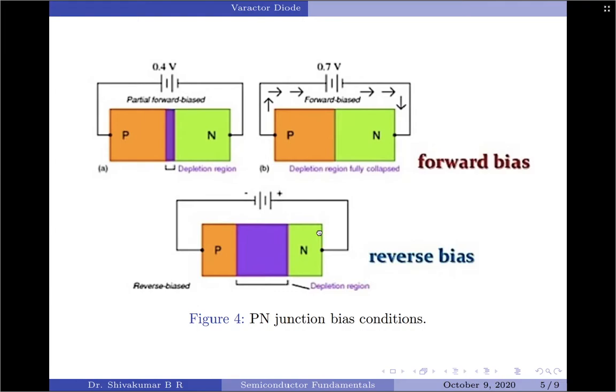The P-type layer of the diode is filled with positive charge carriers and the N-type layer with negative charge carriers. Near the surface of contact between the two layers, positive and negative charges diffuse and neutralize each other. This region is known as the depletion region. The purple colored structure you're looking at here is the depletion region. No further diffusion of charge carriers through the depletion layer is possible unless an external voltage is applied. So, the depletion layer effectively acts as an insulator. The width of the depletion layer depends on the voltage applied across the P and N type layers.